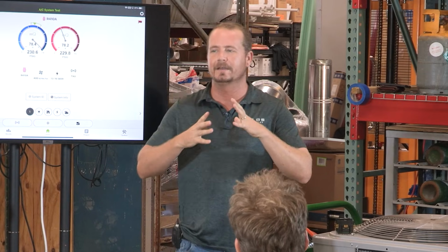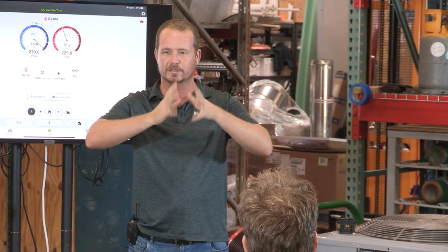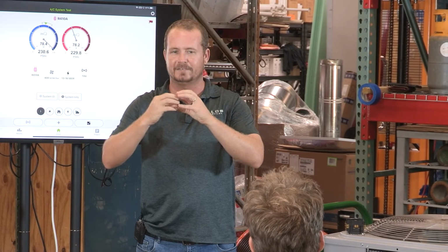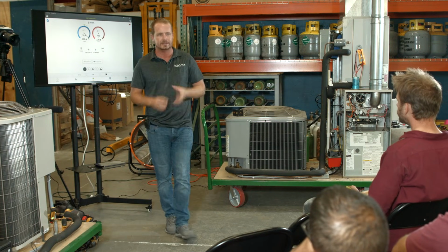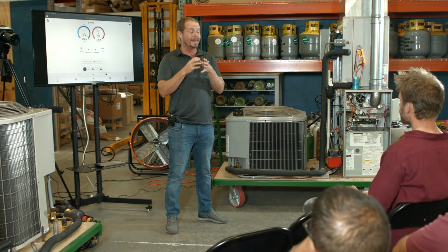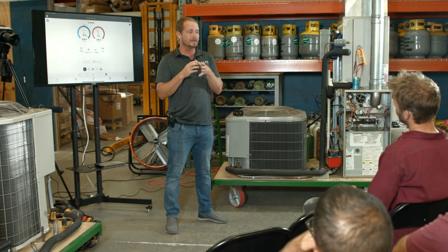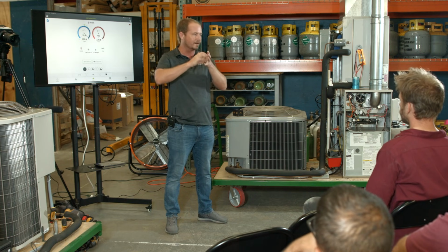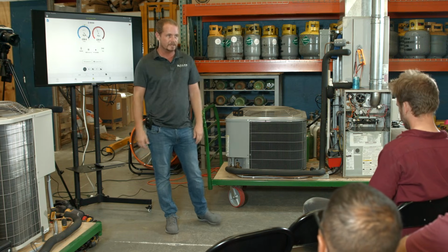Yes, and so what will happen is that either the entire larger hub where it attaches to the blades disconnects, or the internal hub where the shaft attaches to that larger inner hub intersection gets loose. And so when that happens, you'll often get a really loud noise. Sometimes, though, that noise will be intermittent. Sometimes it'll squeal really loud and then it'll stop, and it's just a matter of if it finally caught for a second. But it can be an awful, awful noise.